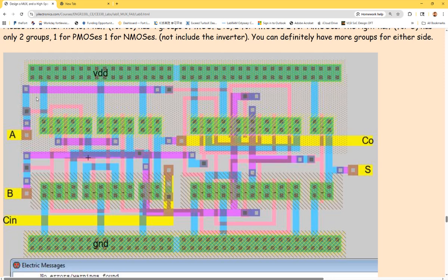Keep in mind, we place all the PMOSes on the top, all the NMOSes at the bottom. It's called CMOS technology because of the complementary MOSFETs, PMOS and NMOS complementary. Forty years ago, people used just NMOS to form logic by putting a resistor on the top, pulling up the drain to a higher voltage to form logic. It's doable, but taking a lot of space. Imagine you don't have PMOSes, but all the N well resistors on the top. Something you don't have to know, but we'll get into more details later.